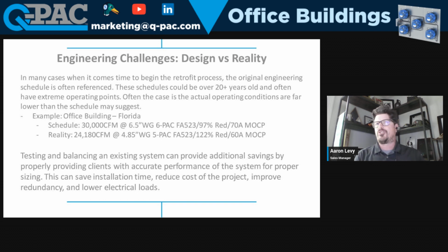So I do encourage that conversation, mainly because the electrical service that's there will be existing for whatever it was. So we should still always be under it. But there's no point, if the system's running at 25,000 CFM, designing it to run 45, 50,000 CFM. It seems a big excess. The chances are they'll never use all that stuff, and they end up paying for more equipment than they need on the front side, which makes the job much more competitive and expensive than it needs to be.